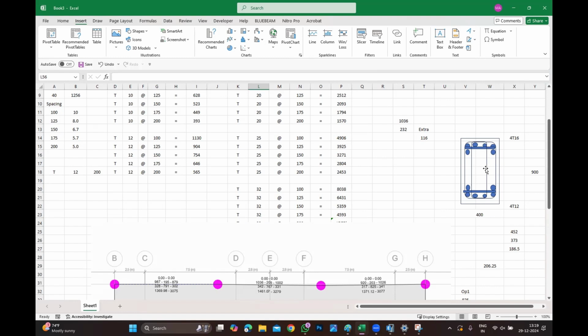Lateral and torsional combined. Imagine when there is a torsional moment, when there is a lateral moment, the whole beam will bend, right? Okay. The whole beam is going to participate. Imagine there is a torsion, two ends are fixed actually, the whole beam is going to twist. So whatever the required rebar which is shown in the model, it is for the whole beam, whereas I do have two sides which are going to resist.